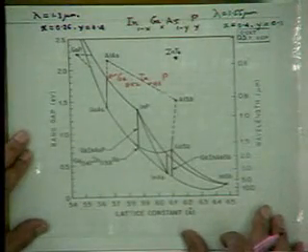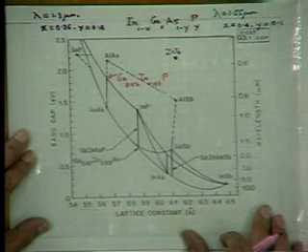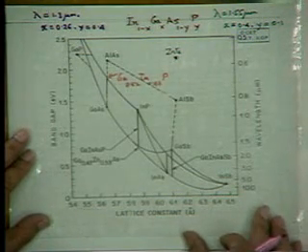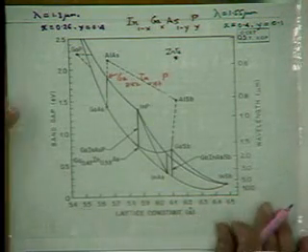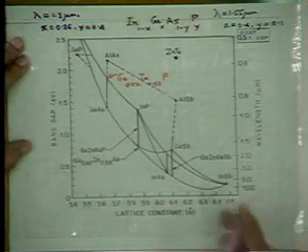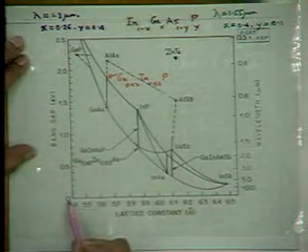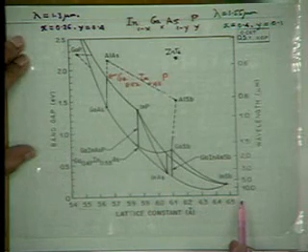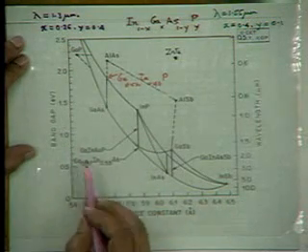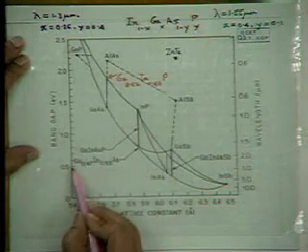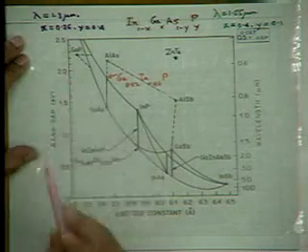And if I just introduce the subject of semiconductors for fiber optics, this is a very important diagram which gives the band gap of semiconductors versus lattice parameter. And if you see, the band gap goes from 0.5 to 1.5 eV.